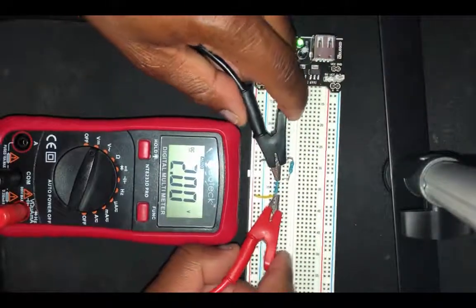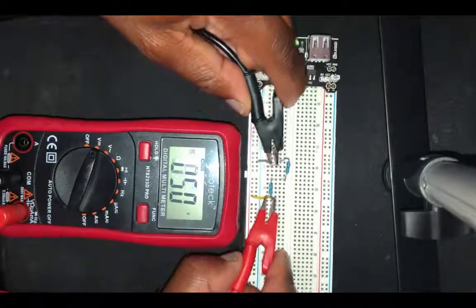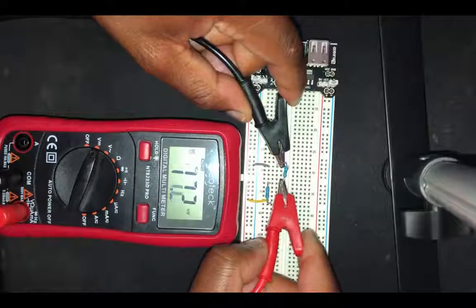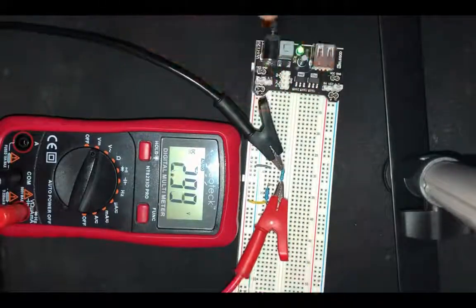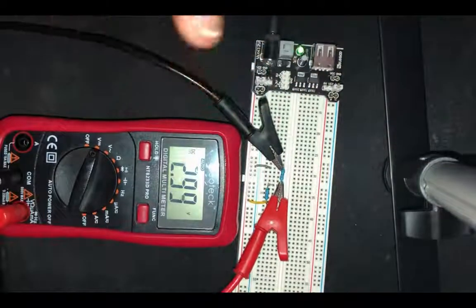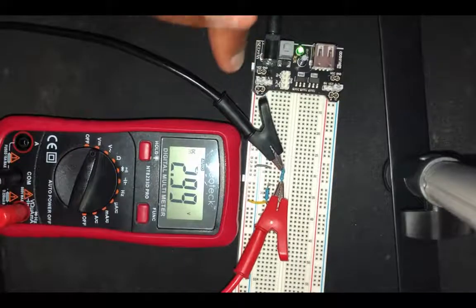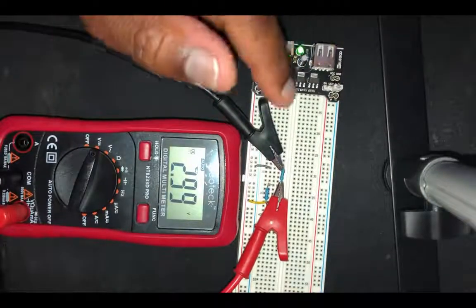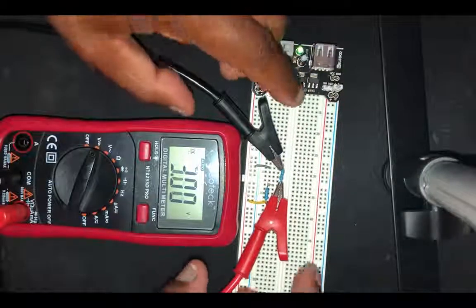That's very good. Now connect it in parallel across the 330 ohm resistor, and we should read 3 volts. And so that's 2.99, that's basically 3. So 3 plus 2 is 5. So Kirchhoff's second law has been obeyed. 5 volts came in, 5 volts was dropped along the entirety of the circuit. Energy conservation.